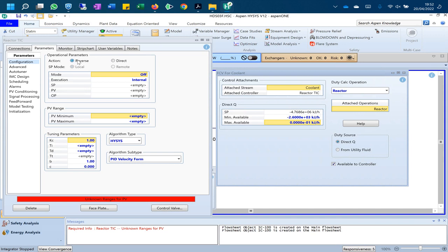When the temperature in your vessel goes above the set point, goes above 60 degrees, the cooling must be higher, must be opened, but this means going to a lower value because it is minimum. So this action is reverse. A higher temperature in the reactor means a response of the controller going to a lower value, reverse action. The parameters I'm going to use are 1.75 for the proportional and 5 minutes for the integral. The set point will be 60.